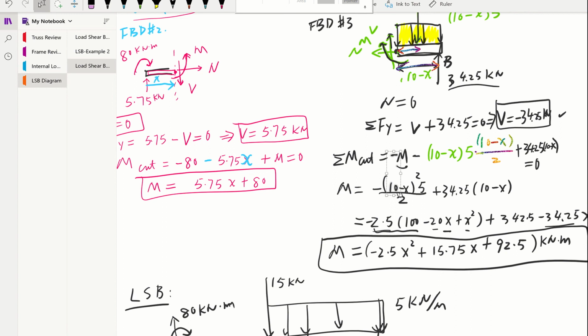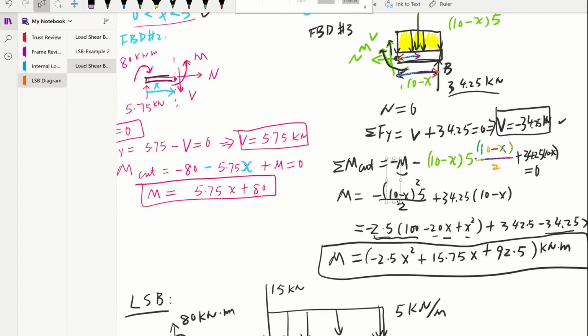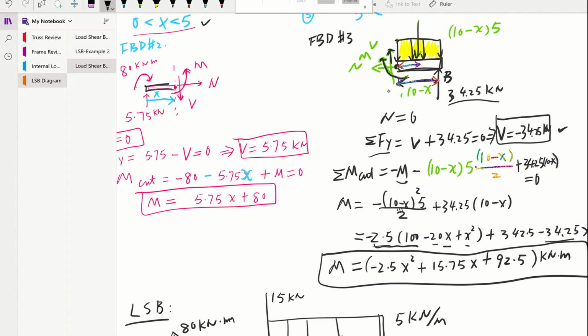Well, hold on for a second. I just spotted the error I made. So let's go back to this shear force. You probably have already noticed the mistake earlier. So when we look at this force equation in y, we have this shear V going upward, and we also have this support reaction going upward, plus, but I'm missing which one? I'm missing this equivalent concentrated load, so I need to add that into the equation.